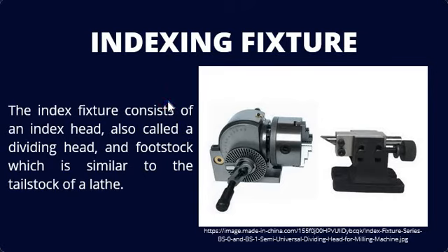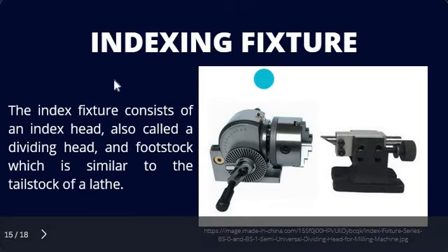If you desire to cut a gear with, let's say, 40 teeth, the number of turns will be 40 divided by 40, which is equivalent to 1.